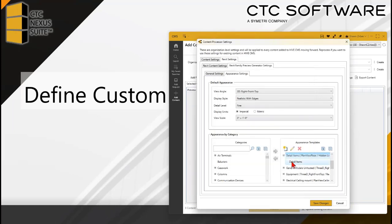And then what I've done is inside of this appearance template, I put detail items. So anything that is a detail item will get this representation. It will completely ignore the default appearance. If it's a detail item, it will do whatever this rule set says. So I'm very specifically customizing how my detail items are being configured.